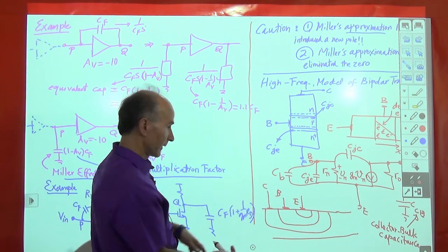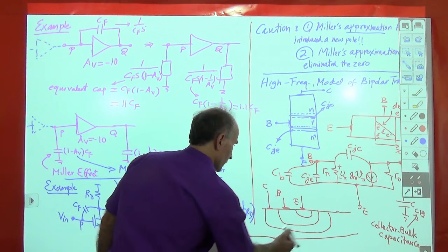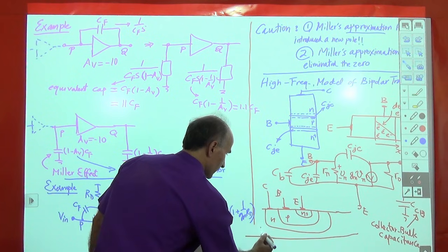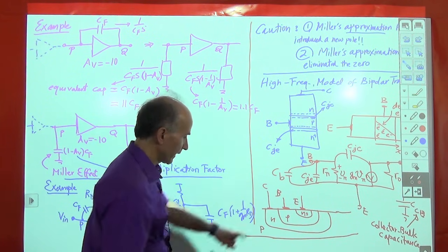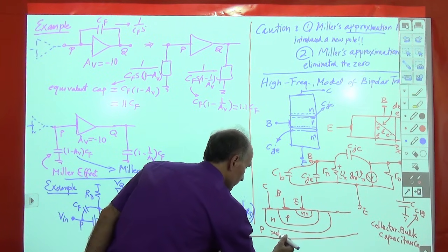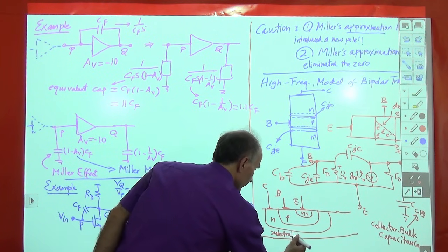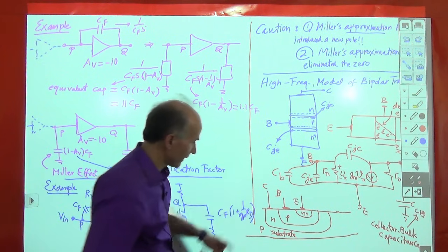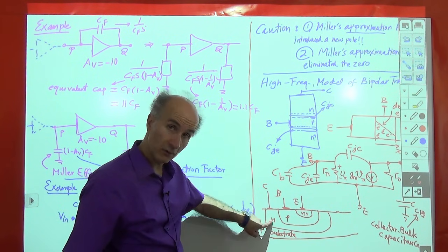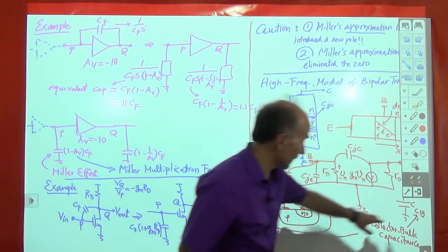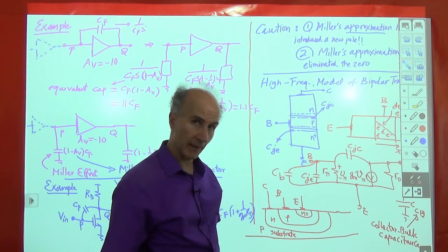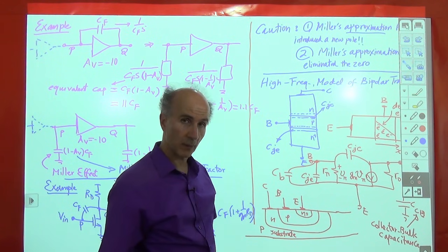Then the wafer is all of this, which in this case would be n-p-n, so this is P. You can see there's a junction between this and this. This is the wafer, we call it the substrate. There's a capacitance between the collector and the substrate because we have a reverse biased junction. So that's CCB, collector bulk capacitance or collector substrate capacitance. The substrate is also known as the bulk.